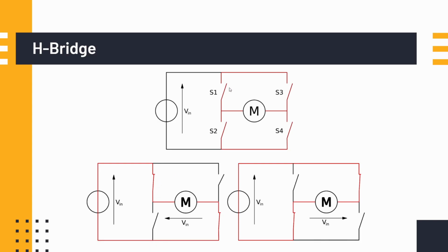Pretty sure. So if you close these two switches, switch 1 and switch 4, the switches diagonally across from each other, the motor is going to spin in one direction. And then if you open those switches and then close switch 2 and switch 3, the motor is going to spin in the other direction. You don't have to worry about this, because the motor driver we're using is going to take care of it.